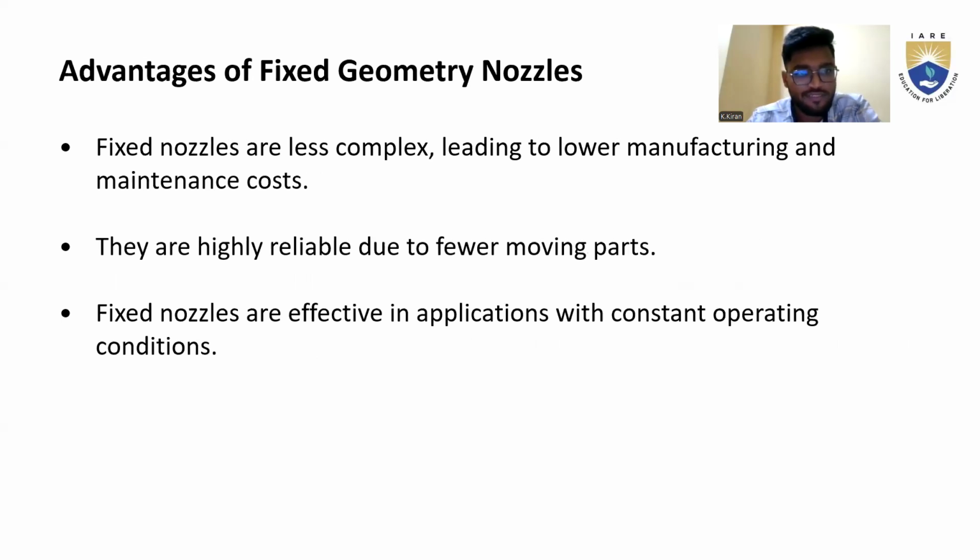Now, advantages of fixed geometry nozzles. Fixed nozzles are less complex, leading to lower manufacturing and maintenance cost. They are highly reliable due to fewer moving parts. Fixed nozzles are effective in applications with constant operating conditions.